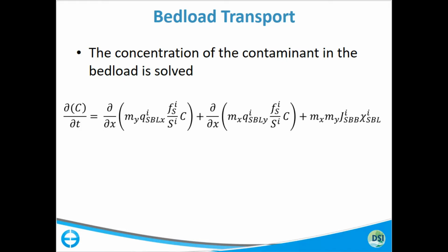And as material is coming in and going out from the bottom through erosion and deposition into the bed load term, I add and subtract to my concentration in the bed load layer. And that just tracks with your sediment in the bed load.